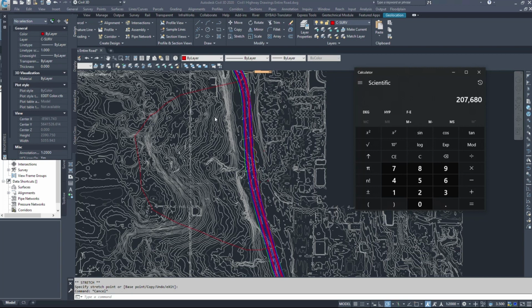Now this would be the amount of water we need to store if our entire section of land here was paved, or the porosity of the material was 0, so that means no water would soak in. Now different materials have a different level of porosity, meaning grass and gravel and dirt will allow more water to soak in, therefore not having to deal with it or pond, than say asphalt and cement and paved areas, buildings,